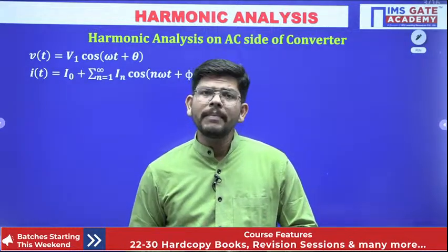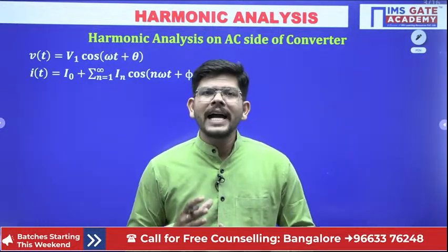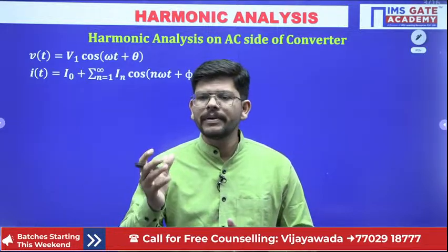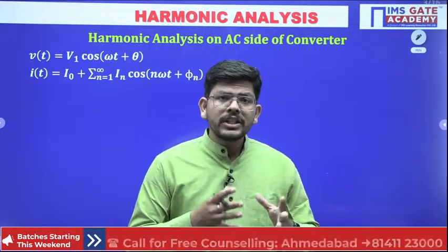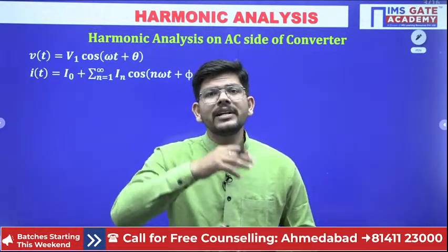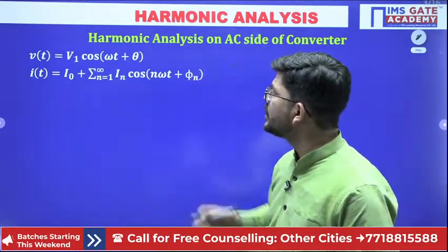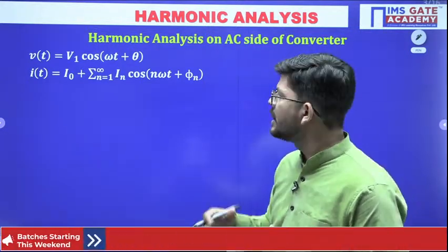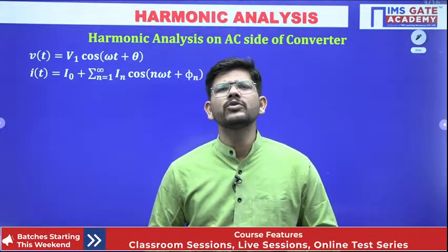So what will happen if the current has so many harmonic terms? Ideally we want a perfect sine wave, but if harmonics are there, the perfect sine wave nature will be lost, and the shape will be distorted because of the harmonics. If the voltage is sinusoidal but the current has many other frequency terms, it might have a DC term, a fundamental term, and many other terms as well.